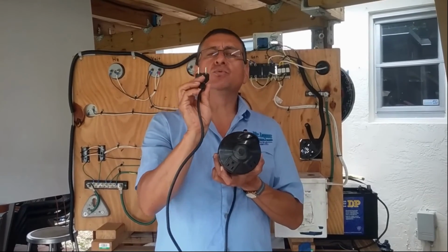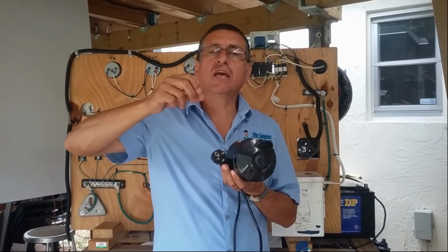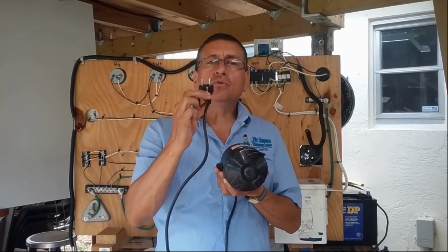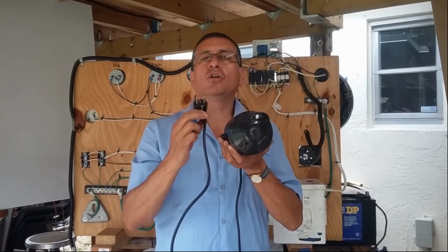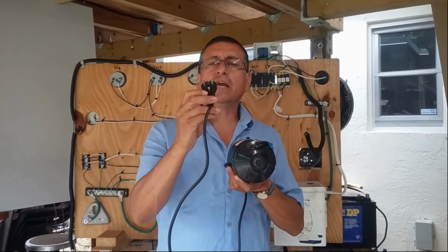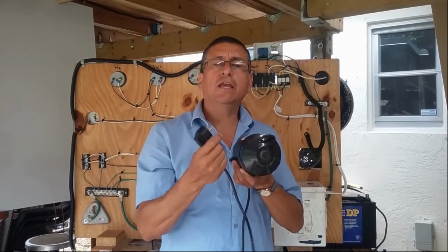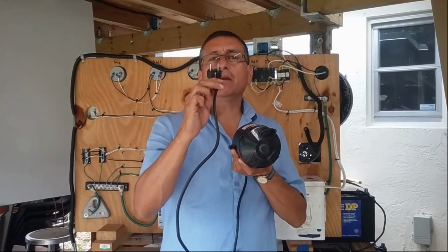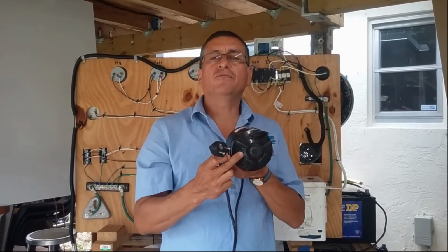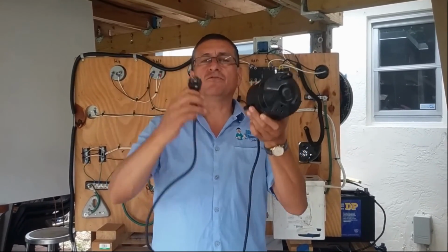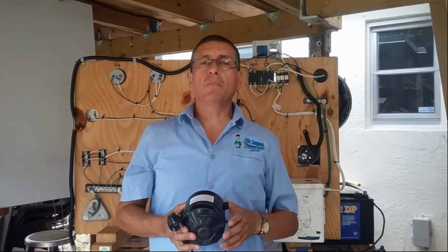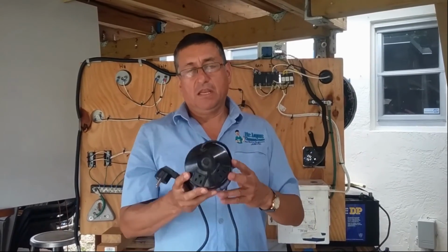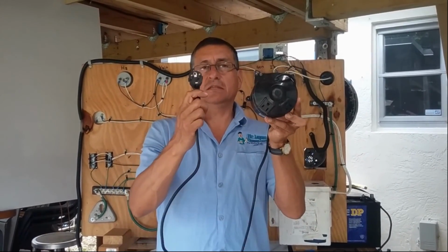The only way to change frequency is when you adjust the RPM on the engine. With the transformer, you only reduce or increase the voltage, not the frequency. In this particular case, we are going to reduce the voltage from 230 into 115. However, the frequency stays constant, 50 hertz and 50 hertz. This is a typical step-down transformer. It's commonly used in European boats in order to reduce the voltage in outlets like this. This is a good example.